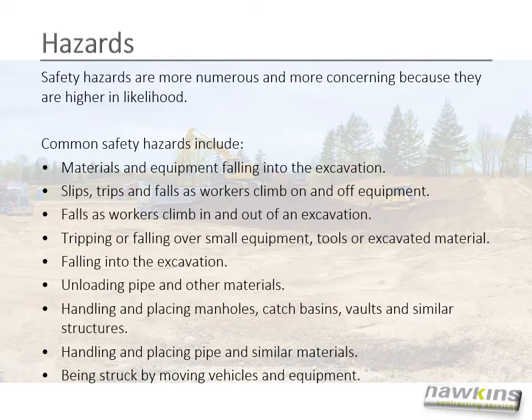Safety hazards are more numerous and more concerning because they are higher in likelihood. Common safety hazards include materials and equipment falling into the excavation, slips, trips, and falls as workers climb on and off equipment, falls as workers climb in and out of an excavation, tripping or falling over small equipment, tools, or excavated material, falling into the excavation from above, unloading pipe and other materials, handling and placing manholes, catch basins, vaults, and similar structures, handling and placing pipe and similar materials, and being struck by moving vehicles and equipment.